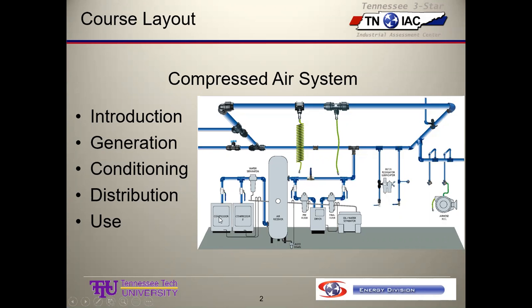We show a couple of compressors, maybe operate one and have one in reserve, which would be a good idea. We're concerned about moisture inside the line, storage tank, and getting into controls and things. So we have a moisture separator right out of the compressors. Then we have an air receiver tank. In this case, this is storing wet air, as we'll learn. We come out and we have some filter.